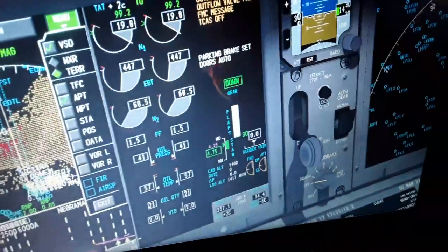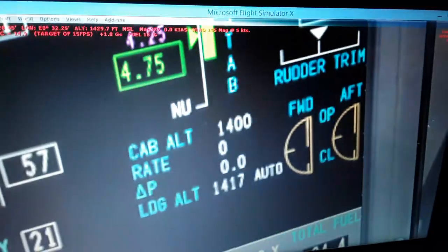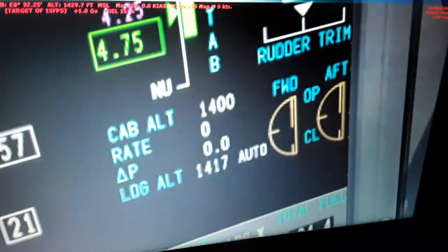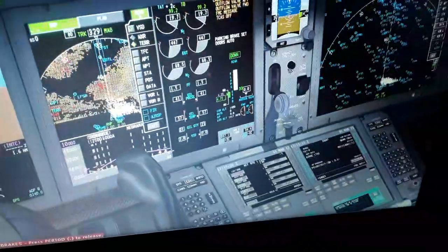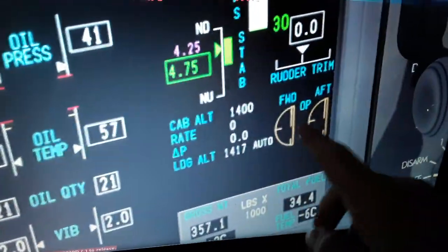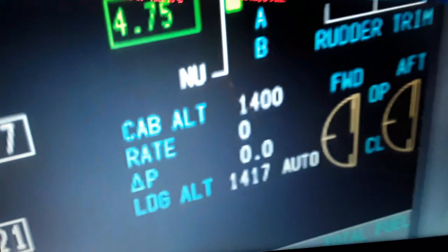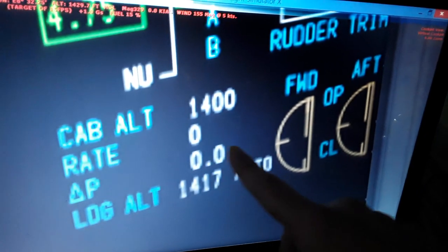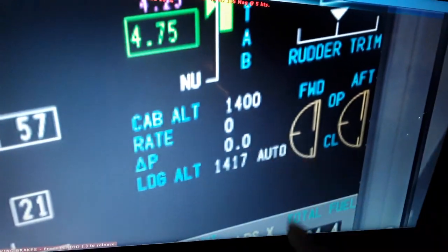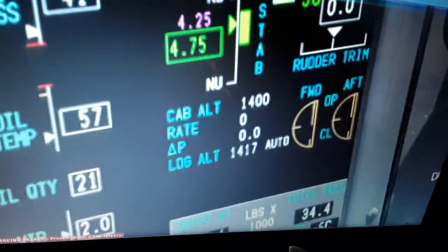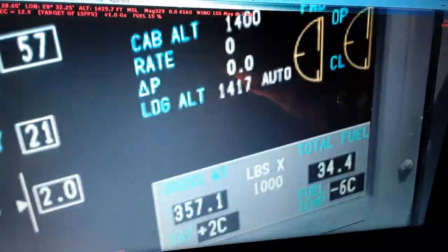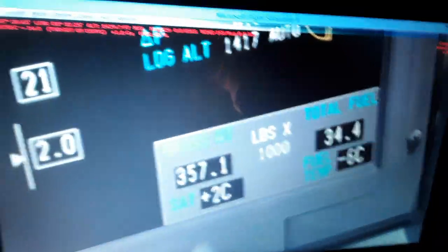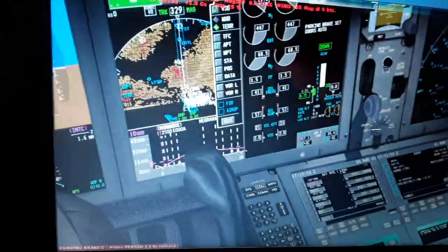We have also the cabin pressurization, differential pressure, cabin altitude. Over here, you see cabin altitude, differential, rate of climb and descent, and the outflow valve positions. So we're going to pressurize the cabin. Differential pressure is going to be 7.8 or 8 psi. It's going to be automatic when we climb and descend, also with the pressurization. You can see here we have gross weight for takeoff, total fuel on board, and the fuel temperature right now.